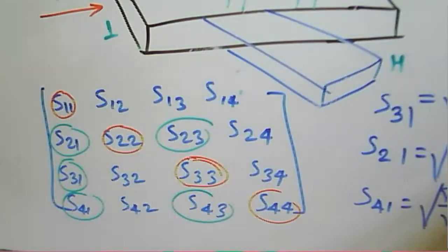If we are using a Gunn diode, it just acts as an oscillator, so along with it we consider a PIN modulator. We'll get the modulated output using the PIN modulator. So we can modulate the 1 kilohertz signal through the Gunn diode, as with the reflex klystron source. So we can use a Gunn oscillator with a PIN modulator as the source, which gives the modulated output, and that signal propagates through the microwave range for the measurement purpose.